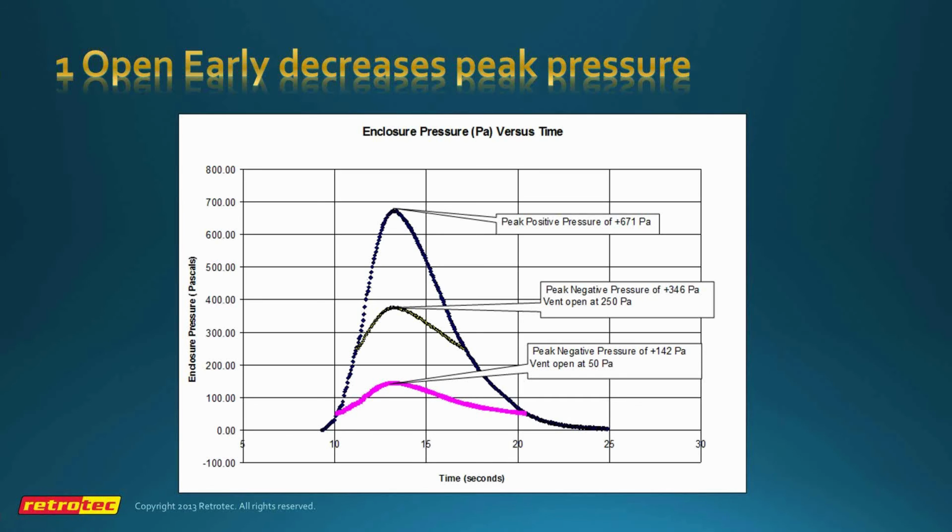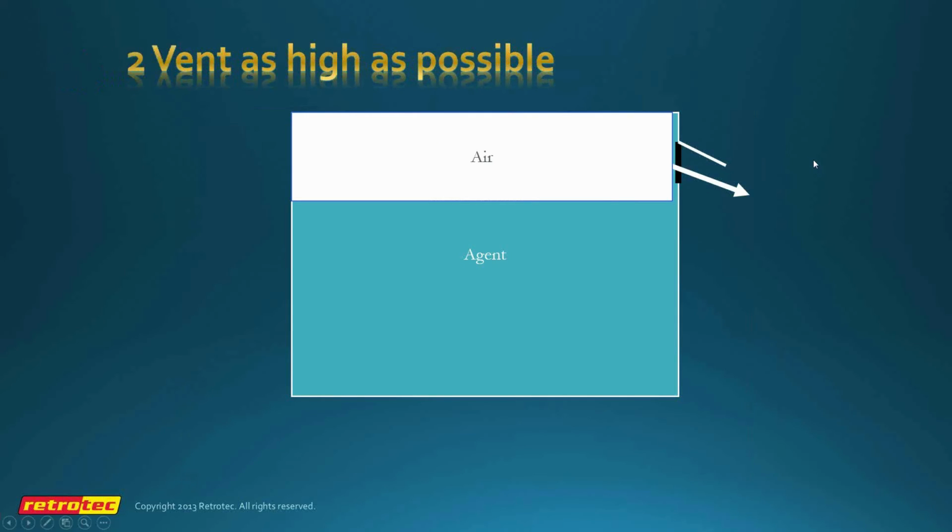For inerts, they happen in 1 or 2 seconds, so you almost don't even have time for the vent to open. If it opens late, you start to accumulate mass in the room, and the more of that that you can vent, the shorter the spike is.